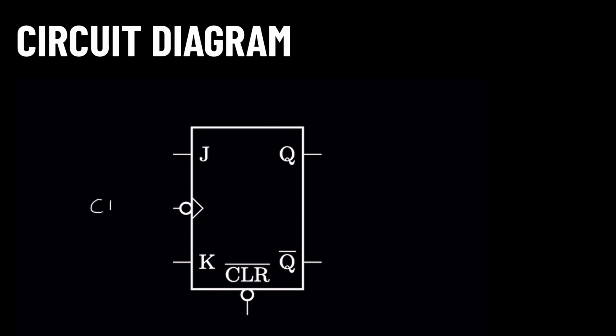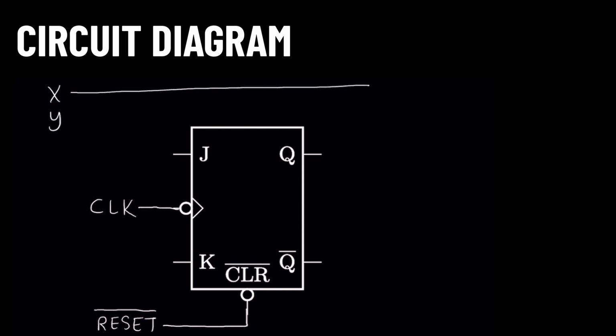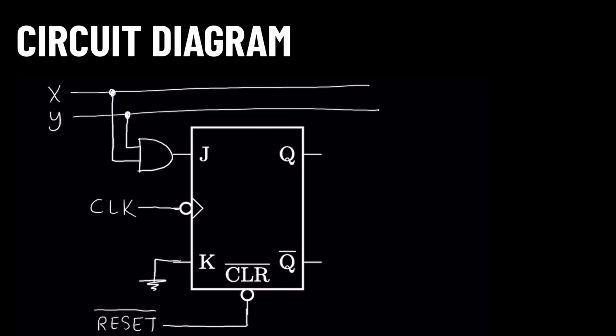How do we wire this up? Connect the flip-flop to a clock source. Connect the asynchronous clear pin to an active low push button. Connect a dip switch or other similar input device to represent the input variables X and Y. Then, using X and Y, the values from the dip switch, and A, the output value of the flip-flop, wire the flip-flop input, then wire the output function.